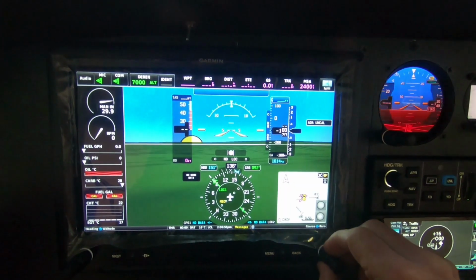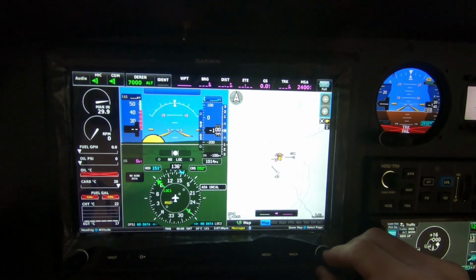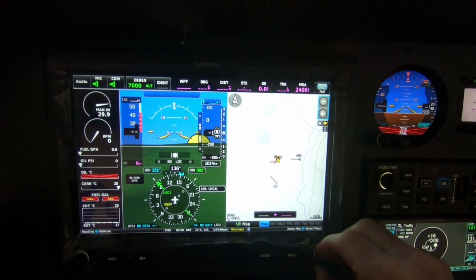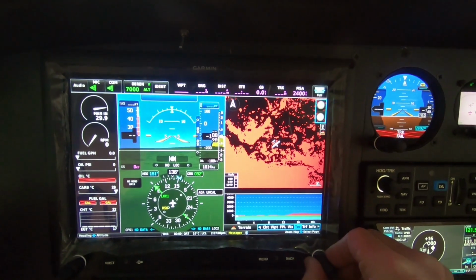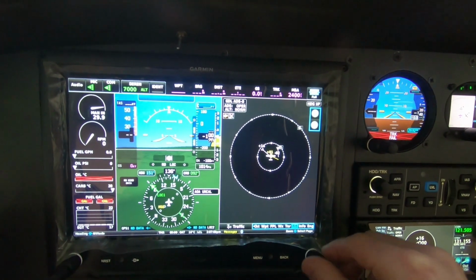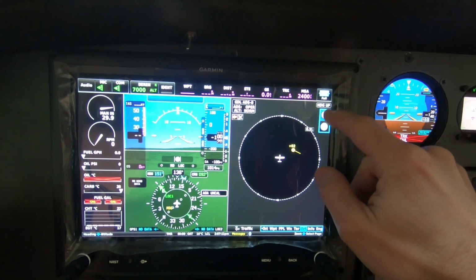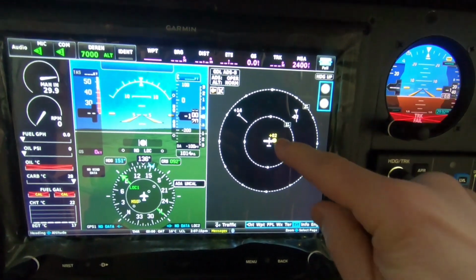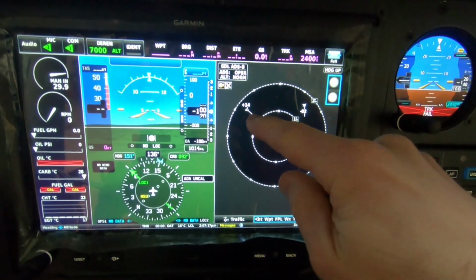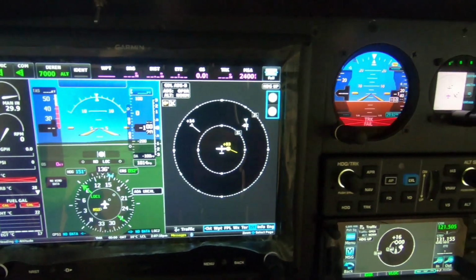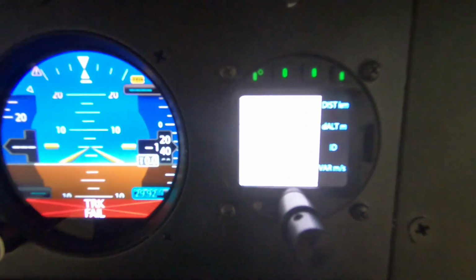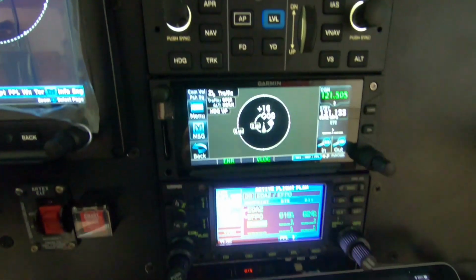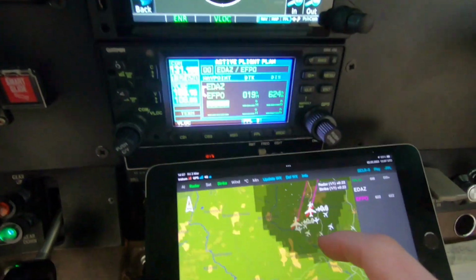Now we have a look at the traffic feature. So in this configuration, we have an AT1 FLARM receiver. We entered 2 demo targets, you see, and a third ADS-B aircraft was just about to fly around the pattern at the aircraft. And we see this traffic information is available on all devices. So we have it on the ADL Connect app. You see the 2 FLARM targets, and we also have it available on the G3X and on the proprietary screen